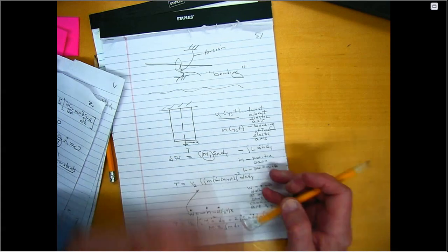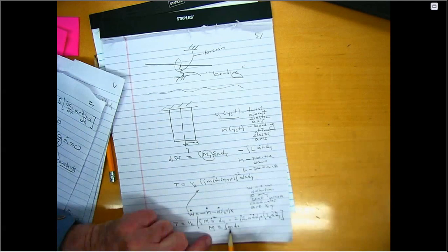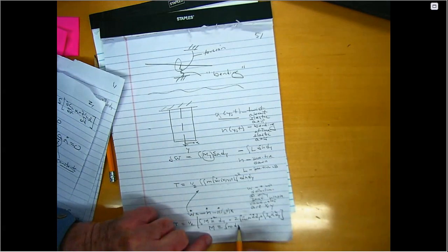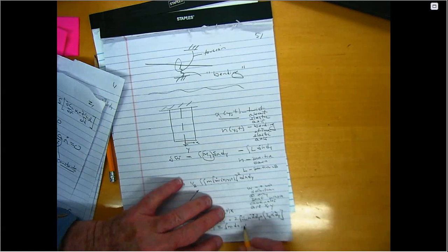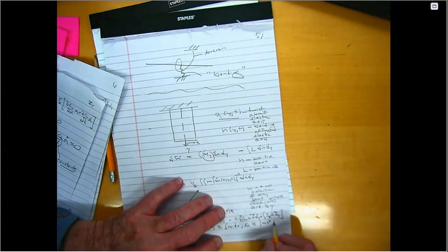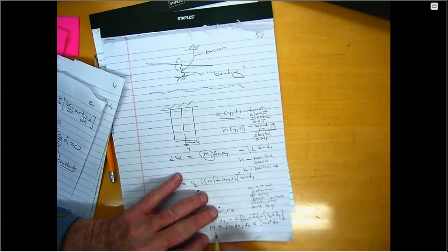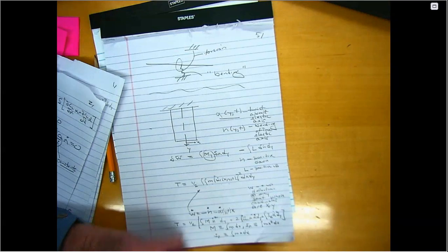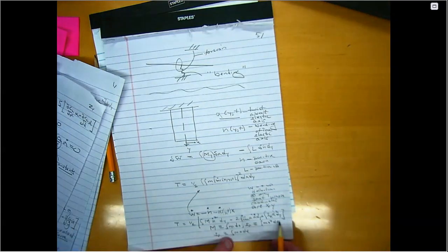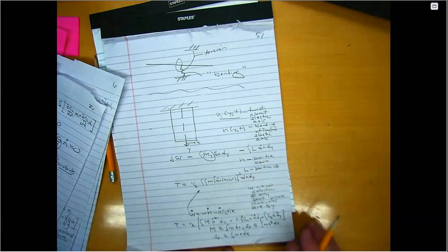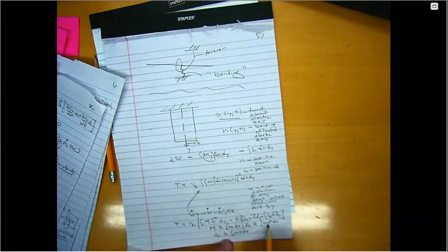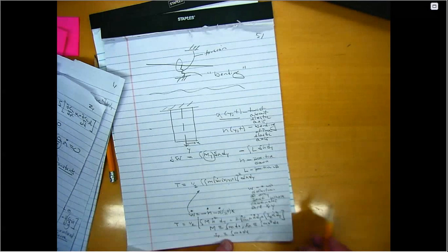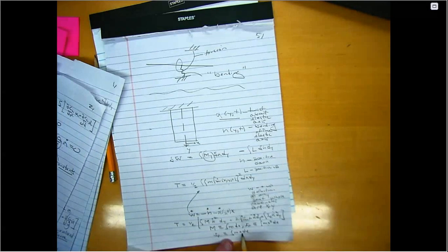So we end up with, because this is mass per unit area and I integrate once, mass per unit span. I alpha will be the integral of m x squared dx, and S alpha will be the integral of m x dx. So these are integrals along x. This is the mass per unit span, this is the moment of inertia per unit span about the elastic axis. And what is this?